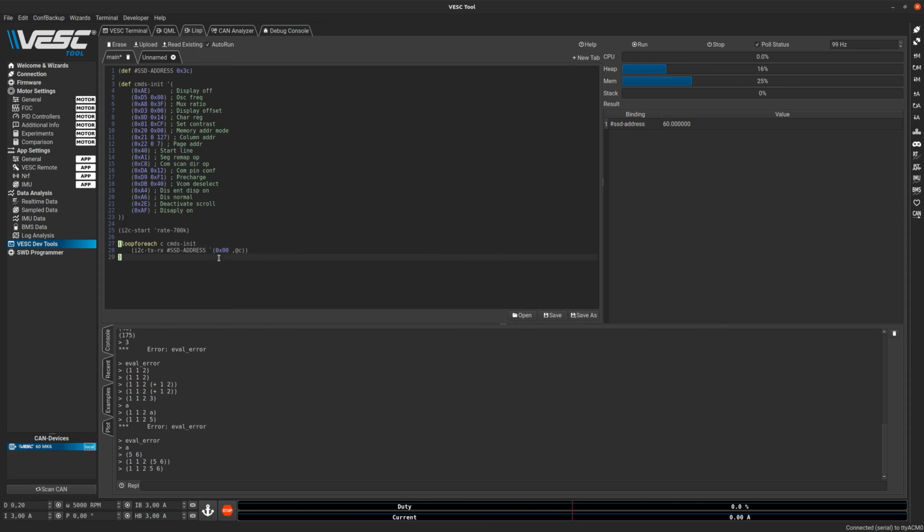So now we have explained the syntax here. So we do quasi-quotation, and we do 0, and then we splice in what is called the element of this that we iterate over every time. The reason we do that is that if you look at the protocol for the display to send commands, you have to send it a 0 first, and 0 means that I'm sending in a command now. After the command, you should have the command and 0, 1, or 2 arguments to that command.